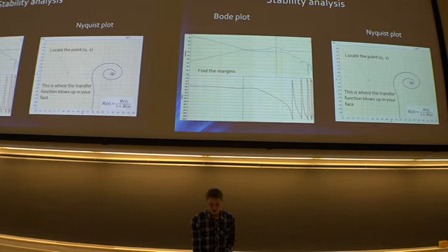Yeah. So how I do this, I generate Bode plots and Nyquist plots. Basically, it's how do you know if the system is stable or not. You can look at the margins. So if you look at the crossing frequency of 0 decibels, what is the phase margin at this point? Because the phase margin is how far away from 180 degrees, that's what you want to avoid. This has a very large phase margin, but you also have to look at the amplitude margin, which is when it crosses the 180 degrees, when it becomes opposite and oscillating, you don't want to have a too small gain.